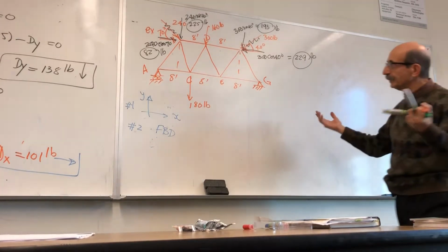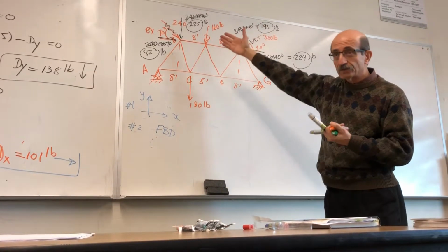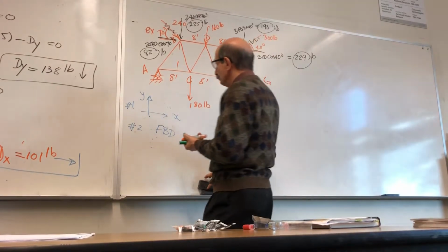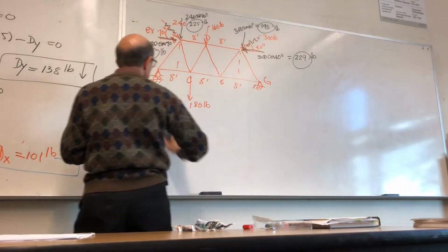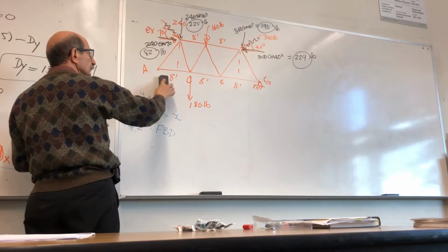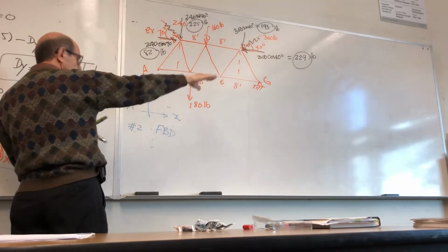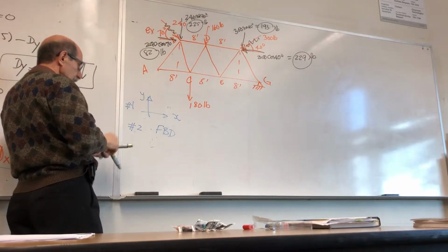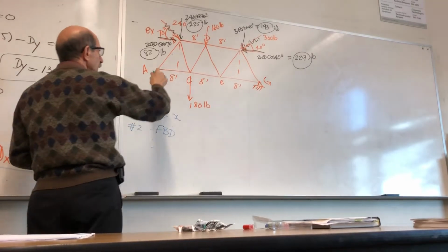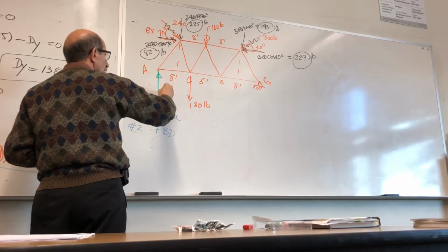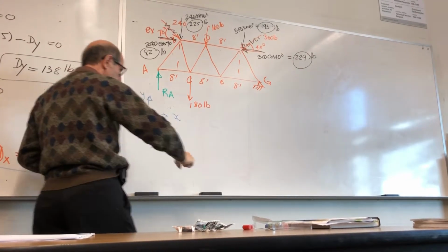So, free body diagram, right? We have those external forces. Remove this support, which represents how many unknowns? 1. Direction of motion is this way, so you have only one unknown perpendicular to the direction of motion, at A. How about this one?